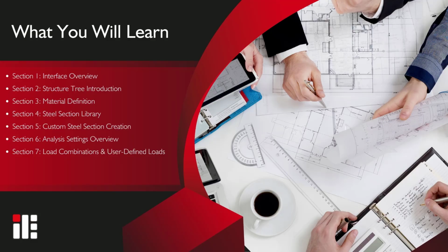Now that we've completed the setup, let me give you a quick summary of what you'll learn in this video. You'll start by getting familiar with the ideCAD interface, including how the ribbon, tabs, and quick access tools are organized. Then, we'll focus on the structure tree, your central hub for managing the entire project. We'll review how to define steel materials, select from standard codes, and create custom materials if needed.